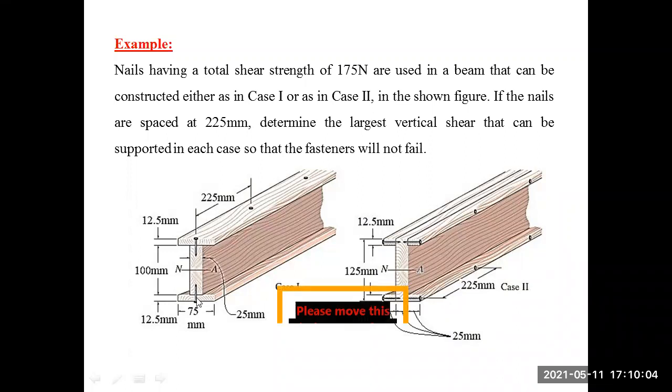The same thing goes for the bottom flange. If you apply a force, it would also have this relative motion that would get it disintegrated from the web, because they are components. They are not a single unit. The flange is not part of this web, and the same thing, the bottom side is not part of the web. So they are fastened, using a rivet or a screw, or maybe sometimes we use glue.